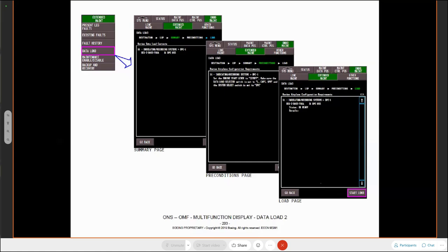It just overwrites it. In the network file server, you will also have the latest version of software because you've just copied it. You may have a previous version, okay? Certainly for things like the flight management computer, you may have one or two versions in there, the current and the previous. If people have been untidy and they've not managed it well for the FMC in 12 months, you may have 12 versions of that same software part number on the network file server. So at some point you're going to have to go in there and start to delete them.